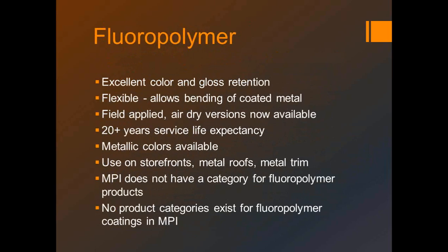And of course, they have very good gloss and color retention for a long period. When we're talking about the hierarchy of paint systems, fluoropolymers are getting up to the tip top. You get into 20 plus years of service life expectancy. So it's not one of the less expensive systems when it comes to cost per gallon.